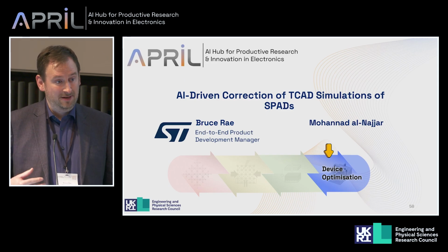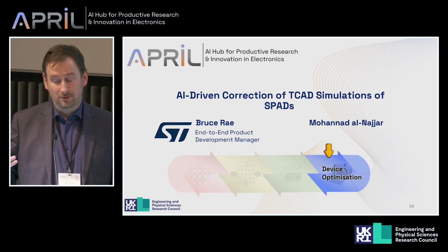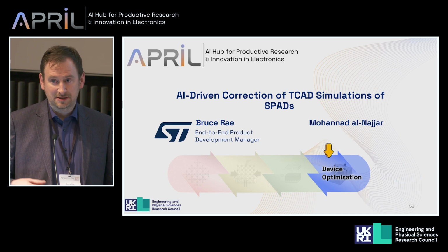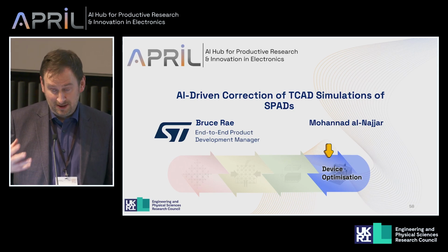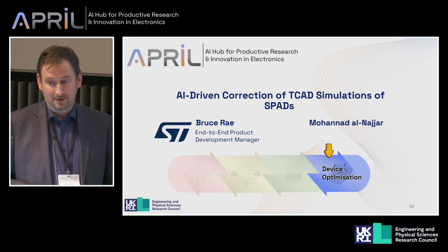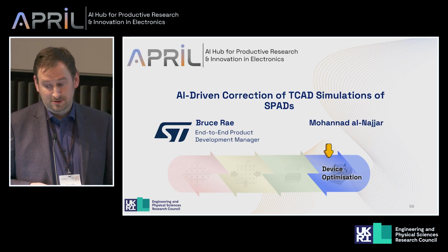So in terms of time to market, the size of the DOEs that we are doing to establish the design of choice, it's essential that we can down select and use TCAD predictably to accurately downsize that DOE and select the SPADs that we want to industrialize.